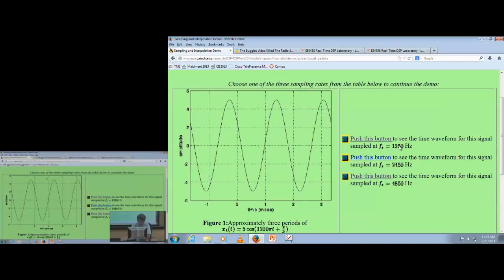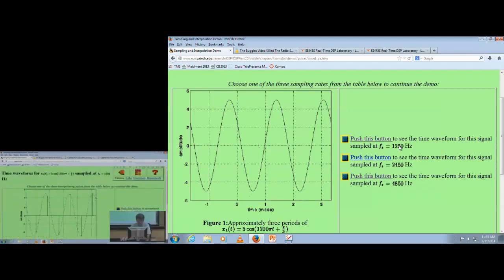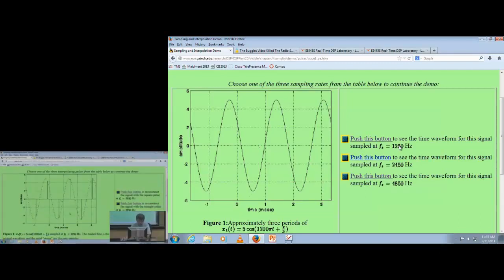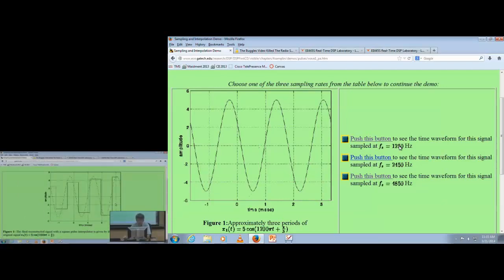Here's the signal in time domain prior to sampling. All this is done in MATLAB originally. So we have slightly more than 2 samples per period of the cosine. You see them here. Again, this one at 0 is missing, but it's really there. So there's a sample there. So I can connect the dots, right, the amplitudes of the samples that I know, using zero-order hold, and I get sort of a staircase approximation.